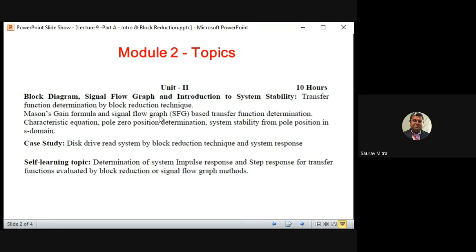So this is a very big statement. By the transfer function we find Y(s)/X(s), and Y(s) is equal to X(s) times the transfer function. Then X(s) can be anything. So X(s) can be found for any kind of input signal. From there we can find out Y(s). If we take the inverse Laplace, we can find out y(t). So if we know the transfer function, for any given input signal, we can find out the output in the time domain. So y(t) can be calculated from the transfer function. These are the significance, the uses of the transfer function.